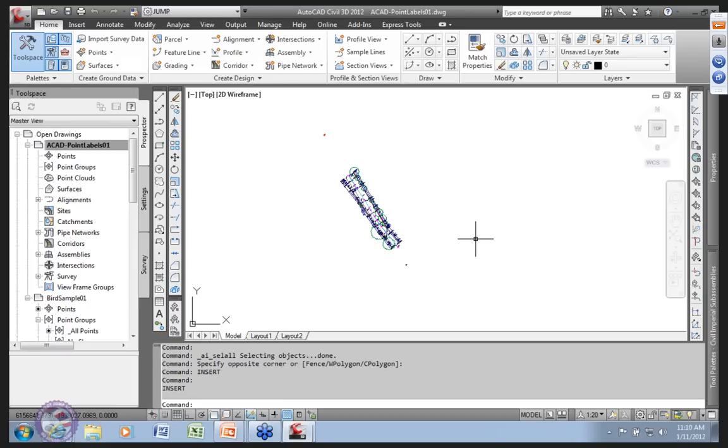And this works for just about every single kind of Civil 3D thing there is in terms of processes. So, exporting point data in Civil 3D and getting it out into AutoCAD. And notice we could have gone to any format. Actually, you can now save as back to other formats. By the way, little key, if you want to manufacture this kind of drawing and do an export to DGN from this drawing, that's also possible, and it will actually do a DGN reference that actually turns out pretty well and is pretty editable. So this process can be extended.